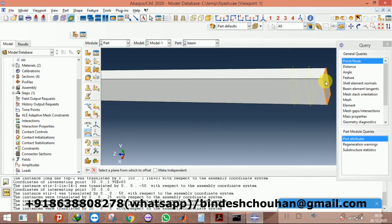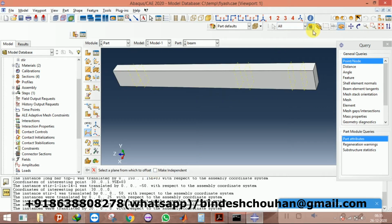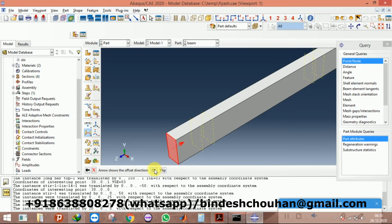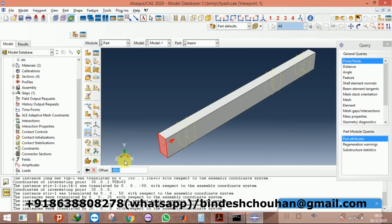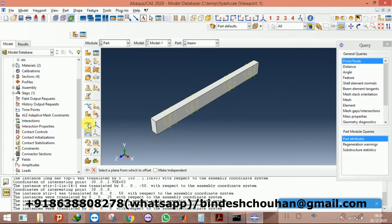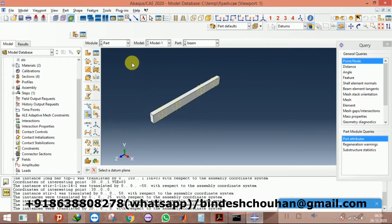So again select this, select 575, done. Here flip it, select 100 again for applying the load. First one was for applying the support, this one is for applying the load. 575, and then make it again 100. And then now I'll just create the partition using the datum plane.